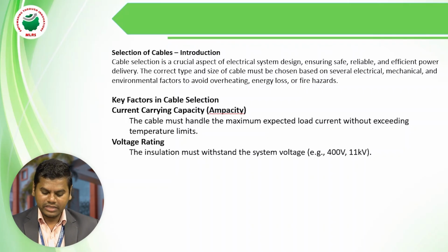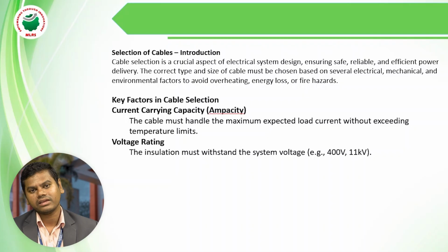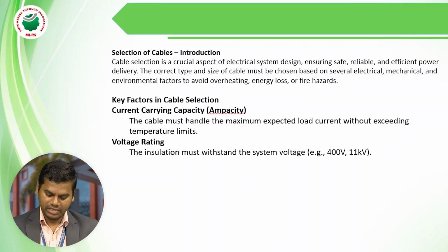Okay, so what are the key factors in the cable selection? The first one is current carrying capacity. The cable must handle the maximum expected load current without exceeding the temperature limits. The temperature here is up to only 30 degrees centigrade.